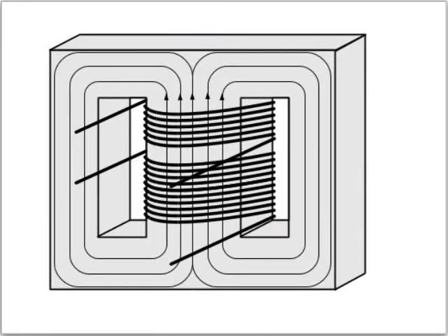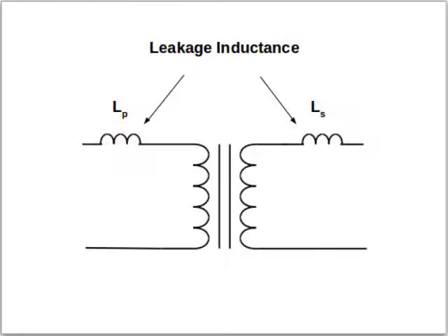Transformer coils are frequently wound around some kind of ferromagnetic core. This is so because it offers high permeability and is cheap to produce. A high permeability means low magnetization current and high coupling, the guarantee that almost all lines of the magnetic field produced by the primary will cross the internal area of the secondary and vice versa. The failure of doing so would mean a leakage inductance in series with each winding. This would affect the ability of the transformer to maintain a good voltage regulation.